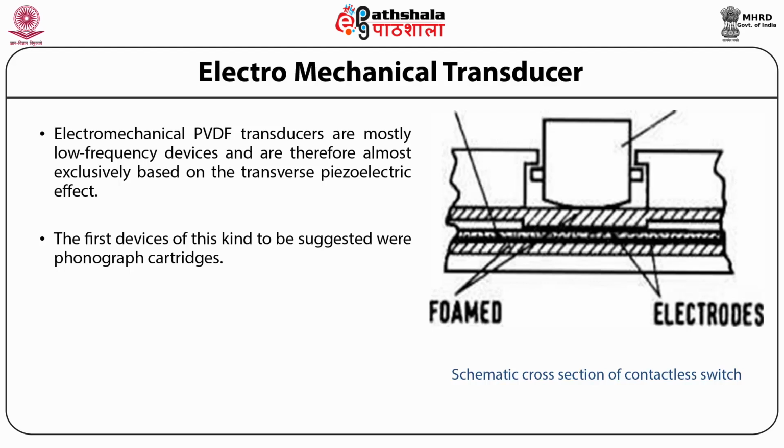The operation of piezoelectric switches, such as the one shown in this figure, depends on the length expansion of the PVDF film due to the pressure created by a push button. The maximum deflection is determined by the elastomer layer, but also may be controlled by a snap disk, which guarantees tactile feedback and a more reproducible electrical output pulse. The basic two-film bimorph structure, also used in electroacoustic applications, often produces insufficient bending forces.